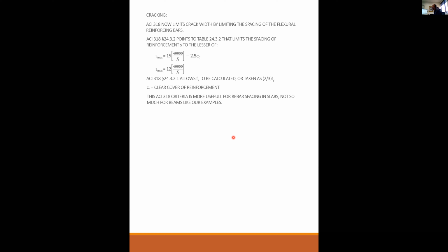Okay, if I give you a beam for an analysis problem, so everything about the beam is known, and I ask you, tell me the capacity of that beam, you need to calculate Mn. And if I ask for the allowable capacity of that beam, you need to give me phi Mn. But you don't actually check it against Mu if I haven't given you any loading.